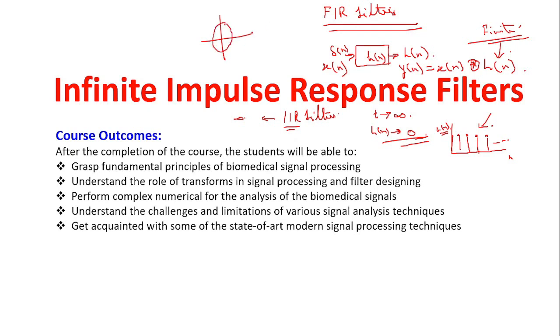This is the real Z and the y axis is the imaginary Z. Okay, so over here we have a pole on the unit circle, and when this kind of situation arises, the h[n] values are neither going out of bound nor coming down to 0. Okay, I have just given you one example.